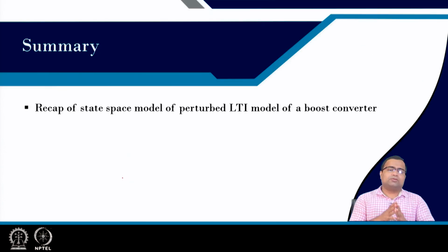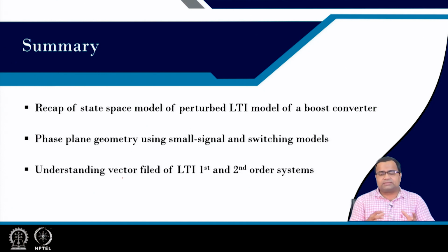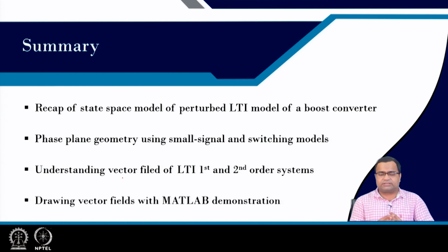So, in summary, we have recapitulated the state space model of the perturbed as well as the LTI model of a boost converter. We have shown the phase plane geometry using the small signal model, but the switch model we have not considered here, that we are going to consider next. Understanding vector field for first and second order systems, then drawing vector field with MATLAB demonstration.